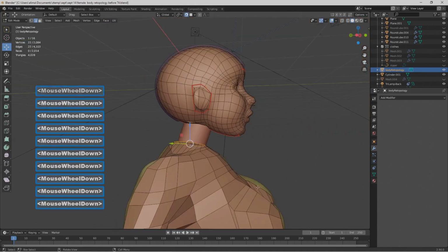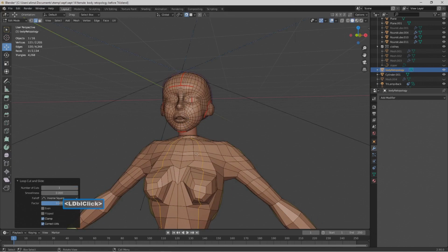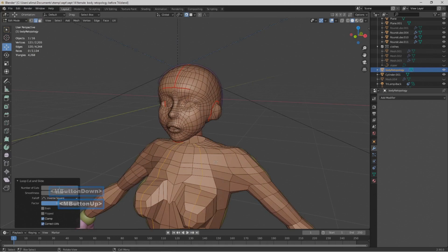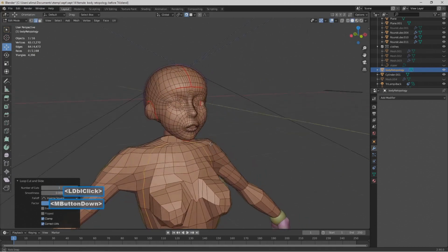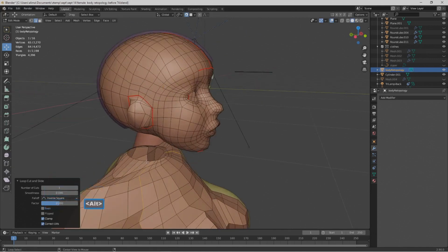So what we'll do is we'll roll back, see where we can put an edge loop in. So we'll hold Control, press R. This should be .24. Now we'll select here, Control R. So now we'll zoom in, hold Alt, left click.